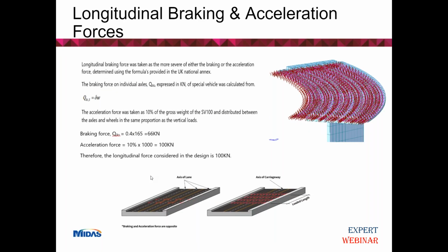Longitudinal and braking acceleration. This was calculated, of course, manually according to the Eurocode, and we got the braking force of 66 kilonewtons and acceleration force of 100 kilonewtons, which was imported, rather put into the software. And you can see here an acceleration force of 100 kilonewtons acting on our deck. Of course, this is a surface force, so in each node we would put 100 kilonewtons of force.